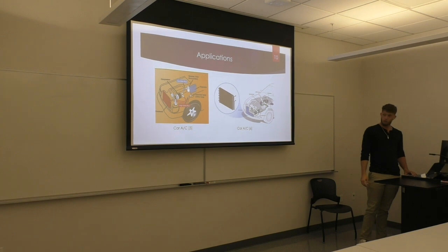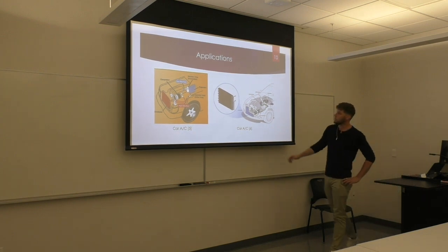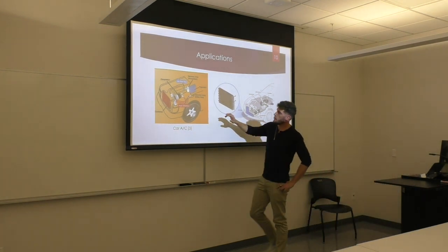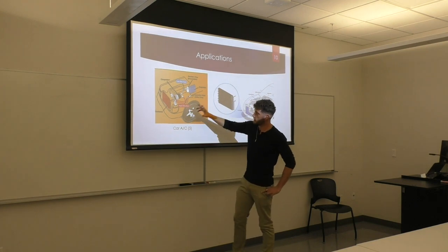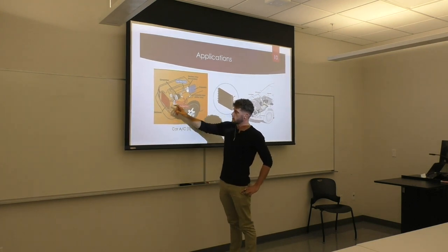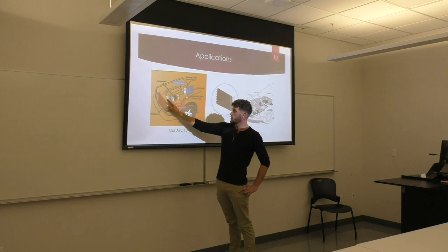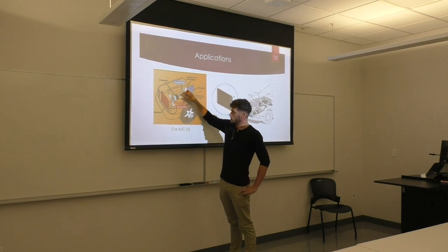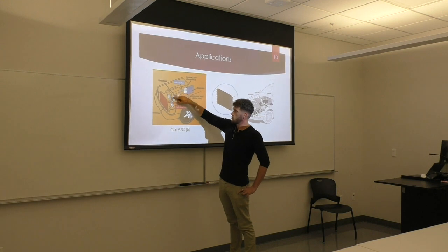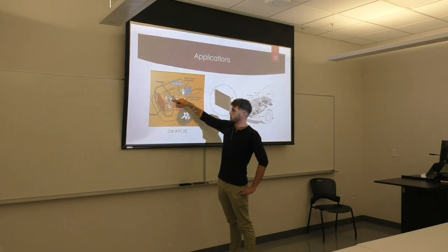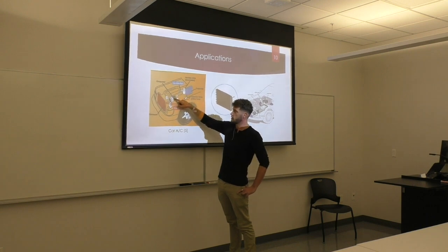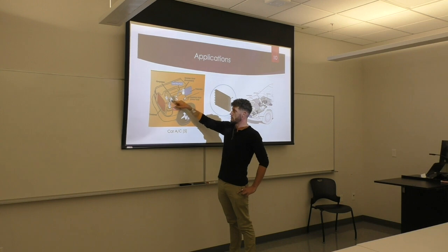As far as the car goes, same system, right? Your condenser, where you're rejecting heat, looks exactly like your radiator. Usually they're stacked behind each other or in front of each other, however that works. Your compressor is going to be mounted to your serpentine belt. A lot of times if you're having problems with your serpentine belt, one of the issues you could be having is that the clutch messed up in your compressor and it's causing it to slip, and you get damage there.